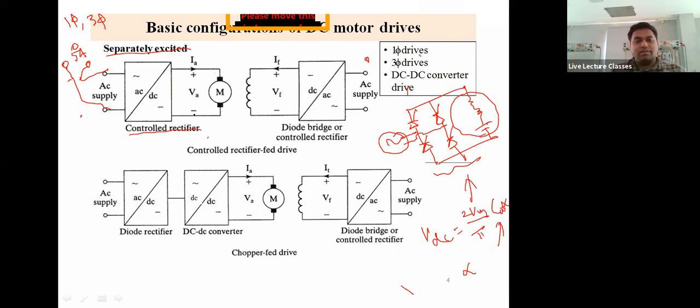So here we will consider this control. We can have a semi-controlled or a fully controlled rectifier. If the power rating is low, we can go for semi-controlled. If the power rating is very high, we can go for fully controlled, right?